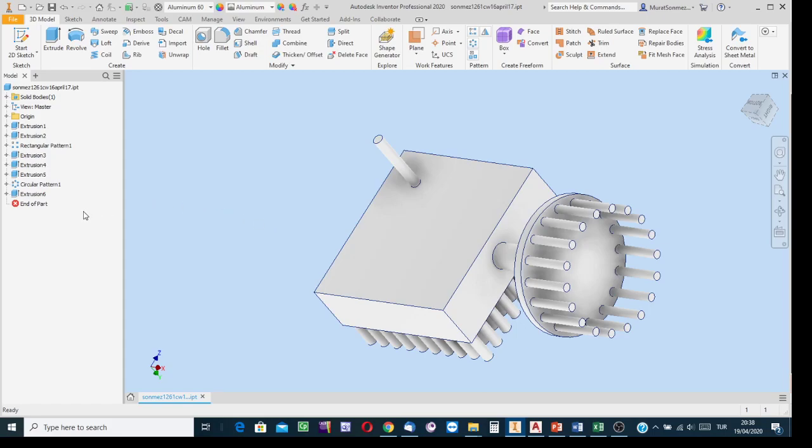So I'm sure that point is in the sketch. Using which sketch, the sketch that created which feature? This cylindrical feature. So find the icon that corresponds to that feature, to be able to make this sketch visible again, since in creating this cylindrical extension I used that sketch, and in the sketch I have the necessary point.